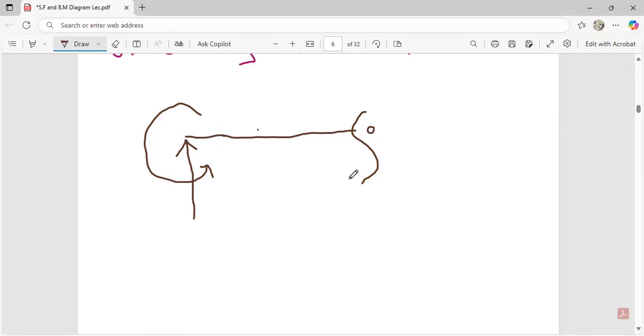So from here to here, let's calibrate it. From here to here, because I cut it, let's just represent it by X, because it has been cut and it is not known. Represent it by X. But we don't know the actual length of it. We have to find out in our calculation. You know that here was our A. VA was what? 225. Please, not the 225 you are thinking of. It is 225 kilonewton.